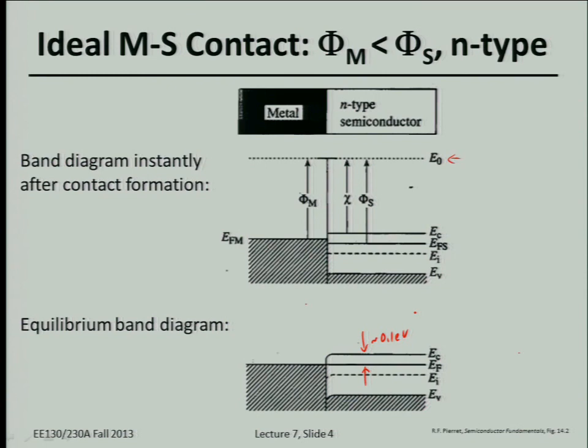Is it fair to say that work function is equal? That's absolutely right. So bottom line is the total amount of energy band bending in the silicon is ideally equal to the difference in work functions. So basically, you're trying to just compensate for that difference in work function. That's exactly right, because the Fermi level ends up at the same level. Starting out, the work functions were different. So of course, the total amount of energy band bending has to exactly cancel out the difference in work function.